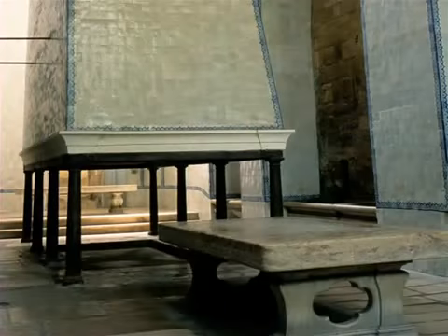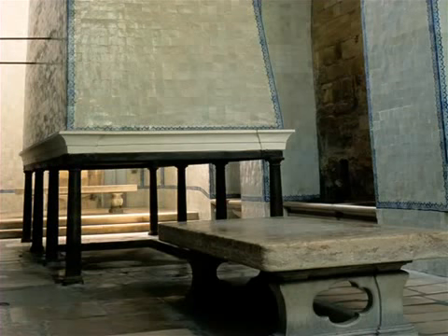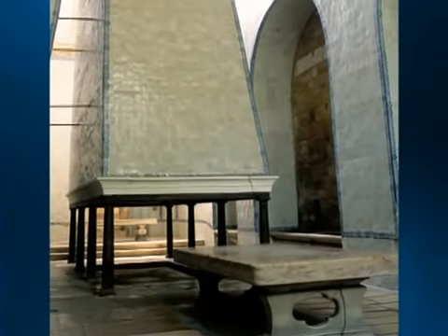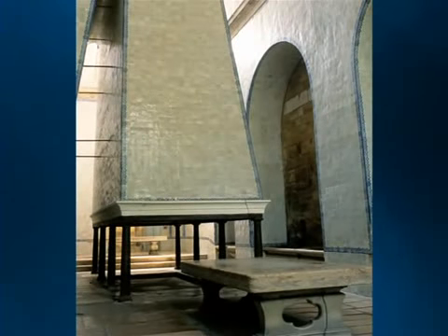Now, with the advent of mass-produced iron at the start of the Industrial Revolution, builders began substituting iron for stone. And the first type of structural element to undergo this substitution was, in fact, the column. The first known iron structural components in a building were cast iron columns used to support a hood over the cooking hearth of a Cistercian monastery in Portugal in 1752. As we've seen, cast iron is quite strong in compression but weak in tension. And since columns carry load primarily in compression, it makes perfect sense that they were the first iron structural components.